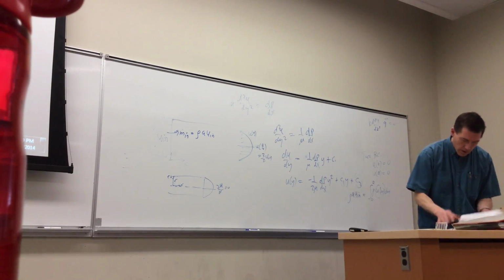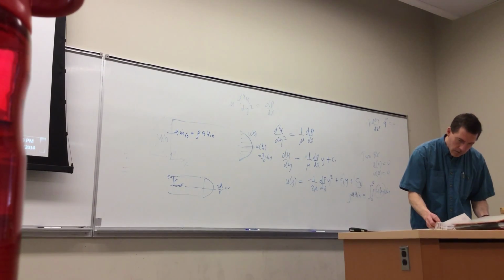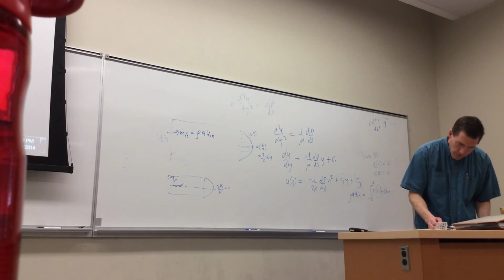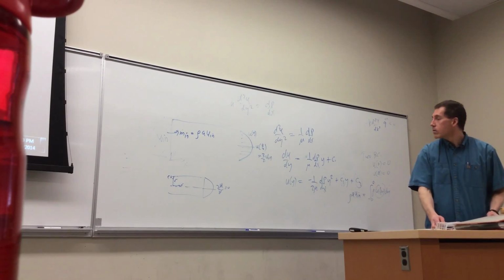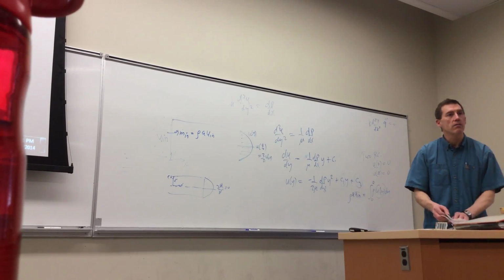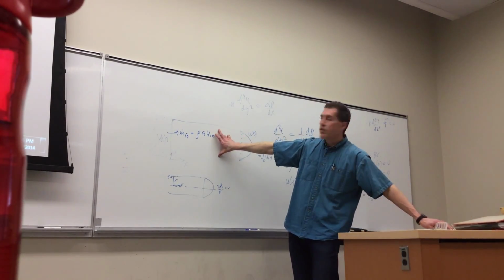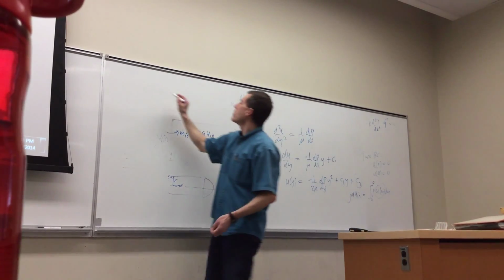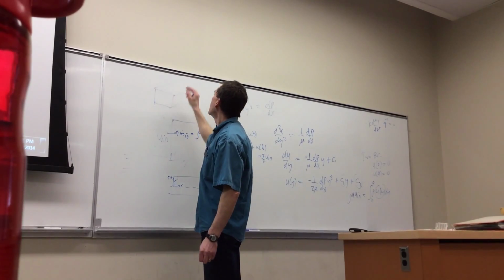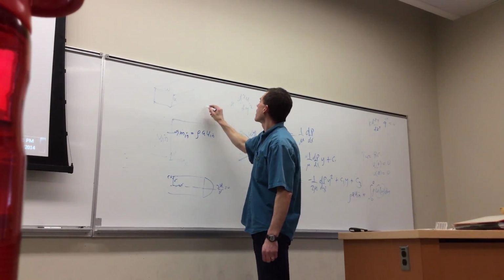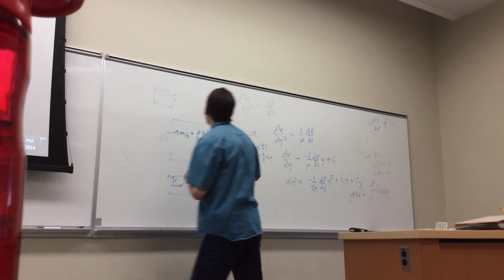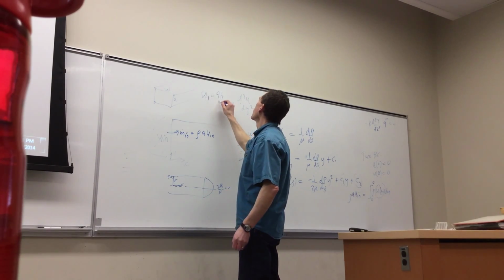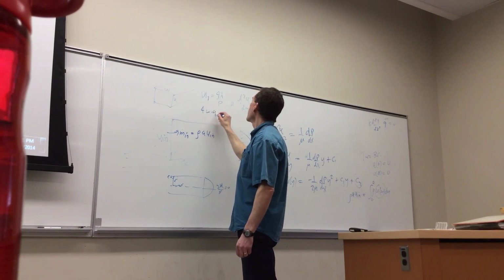So that was 8.4. What was left in 8.5? Or that was 8.5. B part, write an expression for the friction factor using hydraulic diameter. What is hydraulic diameter? Okay, so hydraulic diameter for a parallel plate channel is 2 times the plate spacing, right? Did you get that? If you take a duct and you say this is W and this is A, hydraulic diameter is 4 times the area over the wetted perimeter. So it's 4 times W times A over the perimeter.